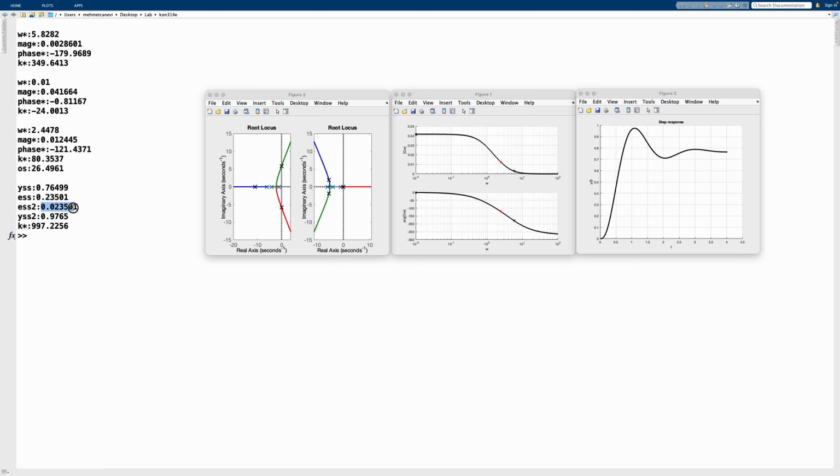And if we want to reduce it by tenfold, we get this value, which gives us 0.97. So it's a dramatic change, by the way, because we're way off of this value, but the lag controller or another p-type controller should force the system to change so that its steady state value should be 0.9765. Now you can see that the issue here is that we are basically out of the stability region.